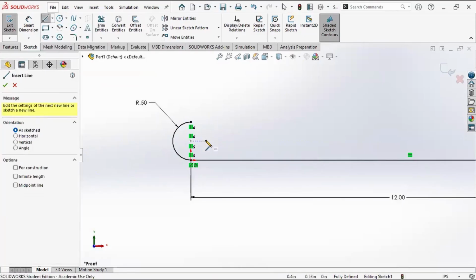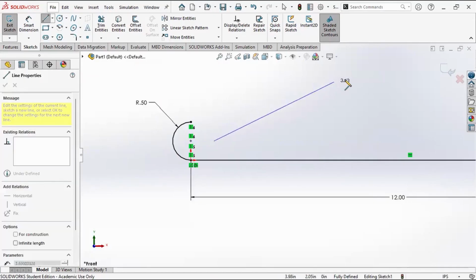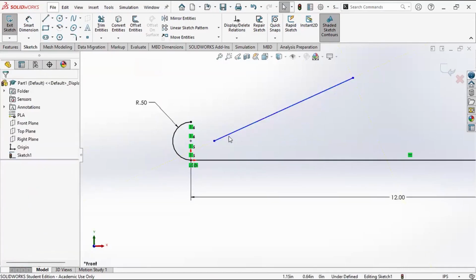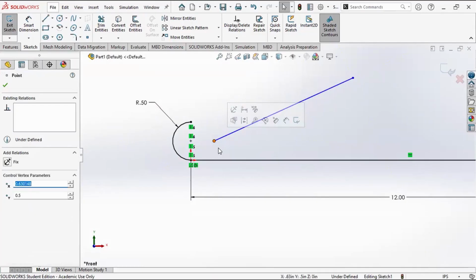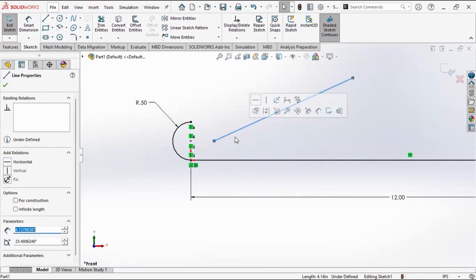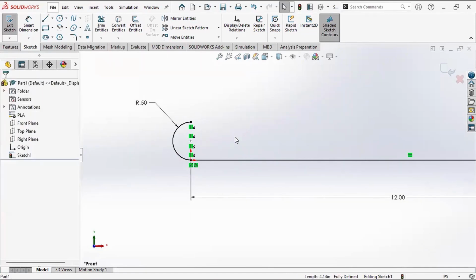But as things get more complex, again, select the line. SolidWorks is going to want to automatically snap to some of these things. And when I do that, occasionally, now it did not in this case, but occasionally what we will run into is it will automatically throw a horizontal relation in here. And that's a thing to watch out for as your sketches get more and more complex. Because what can happen then, well, let's add a dimension. I need to force this to break.